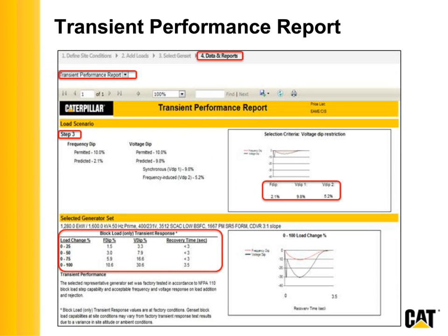So, Stephen, looks like we got another one for you here. How do you print reports for a genset other than the program-selected best fit genset? That's a good question. Really a few too many users have gotten tripped up on that. And remember I talked about on the select genset page, there's a column, factory genset, ekW, kVA.